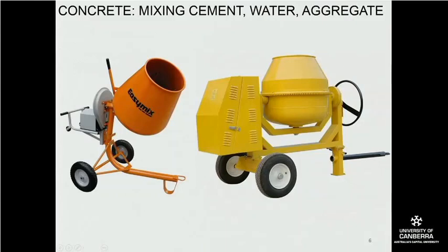Now, once we have cement, then we need to be able to mix it into concrete, because cement powder hardens through another chemical reaction when water is added. And of course, this is affected by climate and environment. It will take longer to harden in dry and cold climates. It will take longer to harden and dry if it's salt water that you use. It may dry too fast if it's in very hot conditions and so on.